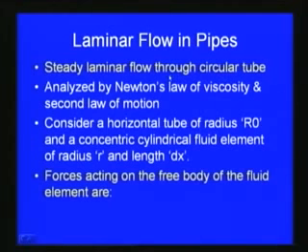First we will be discussing laminar flow, and then we will be discussing turbulent flow in a pipe. So, the first case is laminar flow in a pipe. We consider steady laminar flow through a circular tube, and here again we take the help of Newton's law of viscosity and second law of motion, as we have seen in the previous cases.